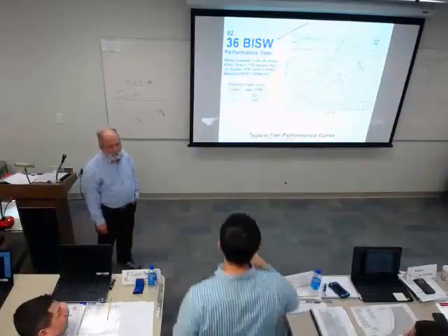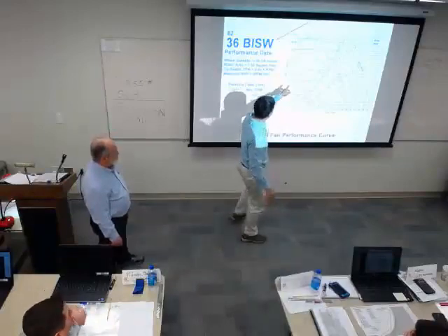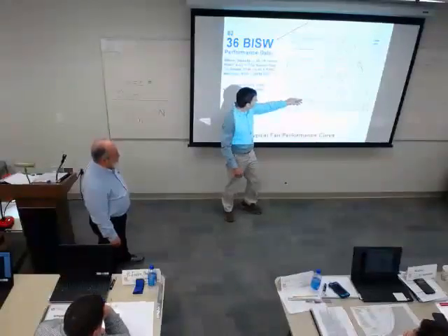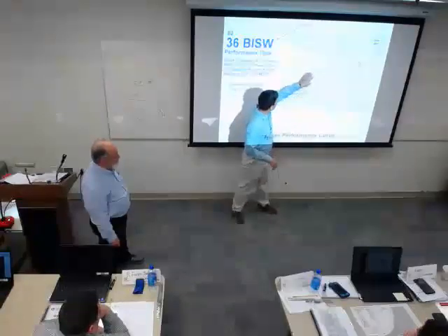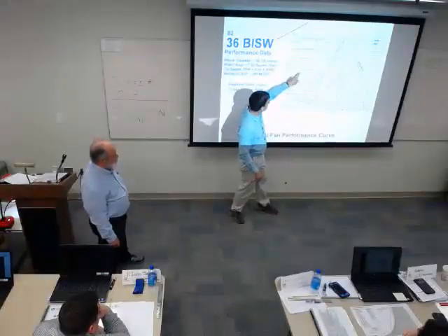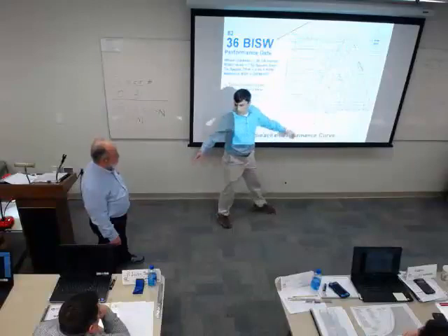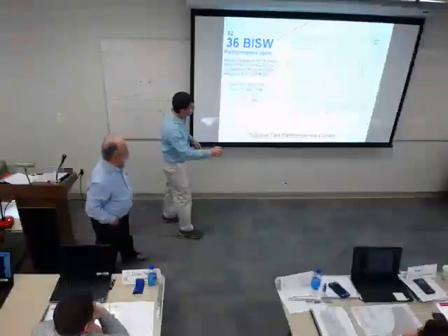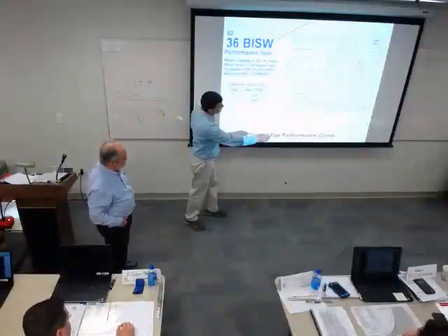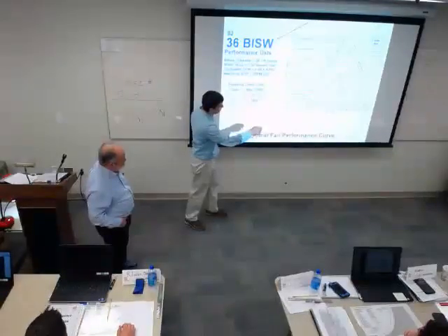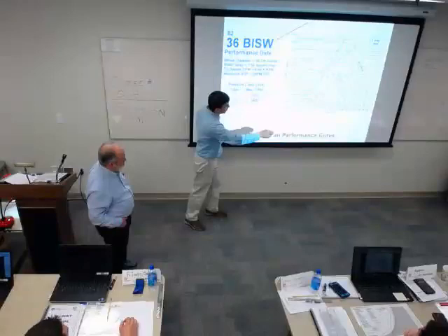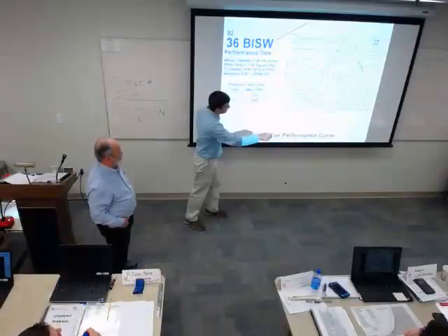The other problem you can have is this. I can look at any point right here and say, all right, this fan... He hasn't got there yet, but while we're talking about this, this is called the flat portion of the curve. On this sloped portion of the curve, he's going to talk more about this in a minute, I can look over here and see my static pressure is this, and correlate that to a flow rate.